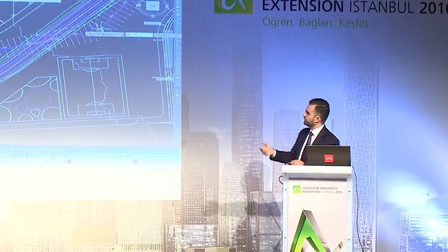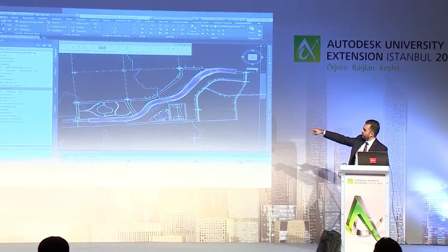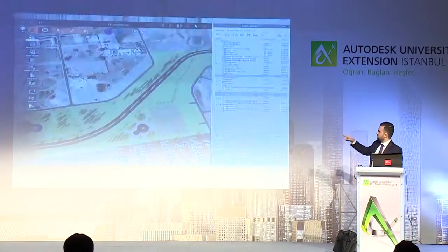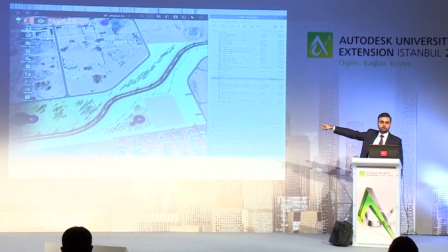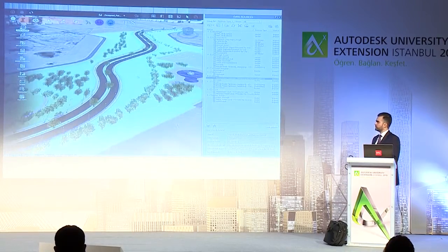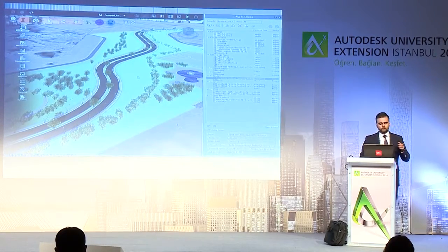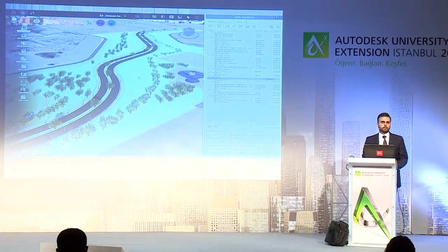And let's suppose that the civil engineer wants to update or change the corridor of the road there, right? We're changing the alignment, we're regenerating the corridor. See what happens in Civil 3D, and with a single click inside of InfraWorks, I'm going to the data source, right-click, refresh, and how that directly updates in 3D live. So the way things are being done now in infrastructure has changed with InfraWorks. You're able to do things in Civil 3D, push them to InfraWorks, and show it to your customers in a very visually compelling way.